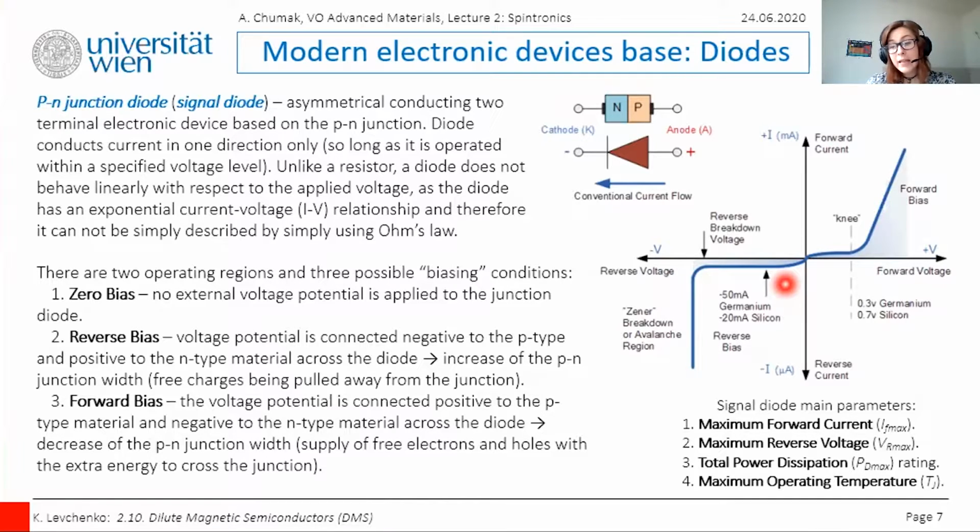As the diode can conduct from this point an infinite current, it again becomes effectively a short circuit. Therefore, resistors are used in series with a diode to limit its current flow.